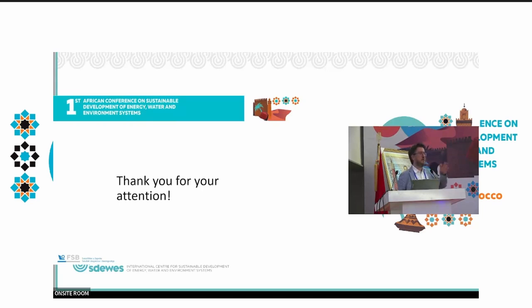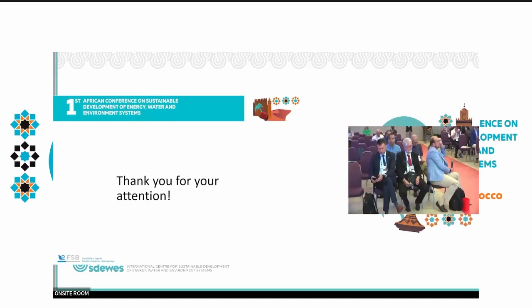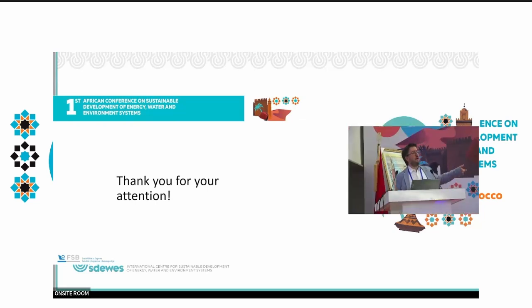We have very strict building codes that define how we need to build buildings, and one of the cornerstones of these building codes is what type of material you can use and what kind of insulation you need to put in. So technically it's more or less done. If you're building a new building, it's basically a nearly zero energy building. You have architectural freedom to use different kinds of architectural solutions. So you can position your building so it has beautiful glass surfaces towards the sun, to decrease the heating demand during the winter, or have different kinds of shading options to decrease the solar gains during the summer.